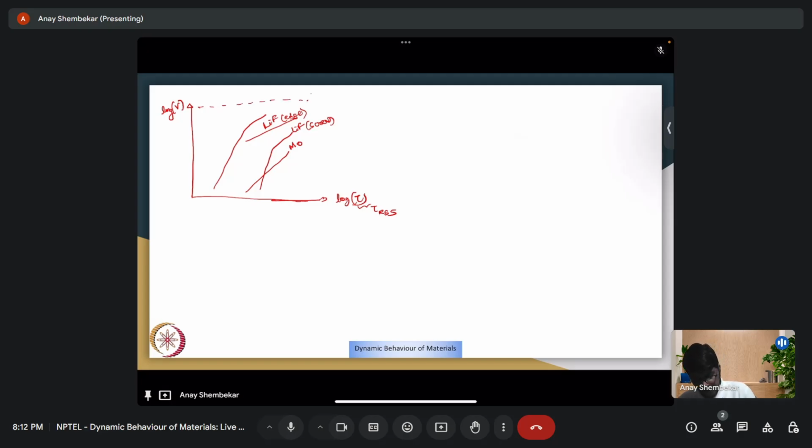So there seems to be an upper limiting value. To the instructor's knowledge, there has not been reported a dislocation velocity moving faster than the shear wave velocity in the medium. We also see that as the velocity increases, your slope decreases.